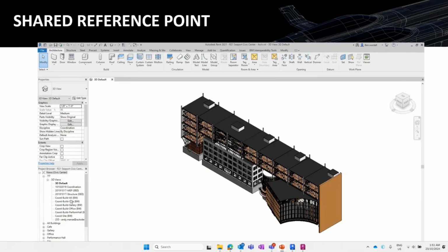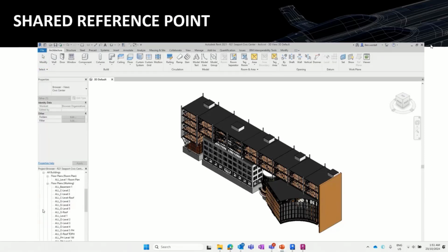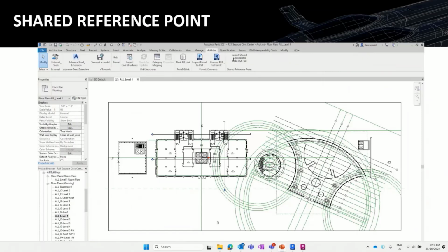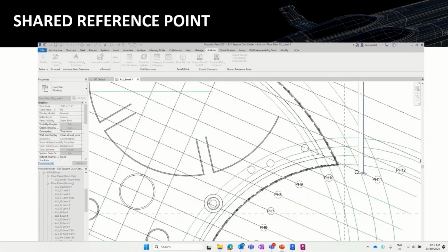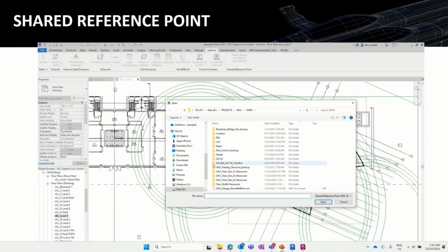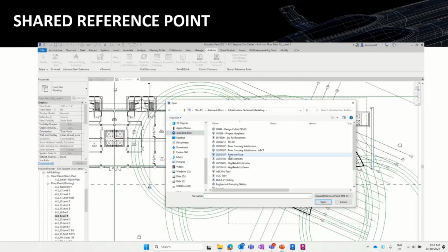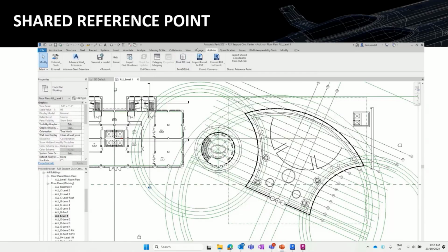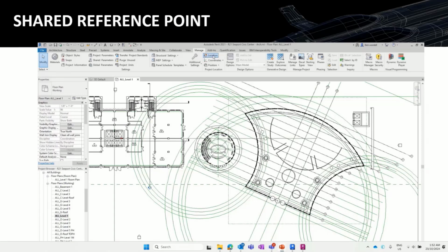So what you need to do now, remember, we already downloaded that add-in from the extensions. You need to go to the add-ins, Import Check Coordinate from XML file, and from there, when you import, you need to select a point to place the surface layout.